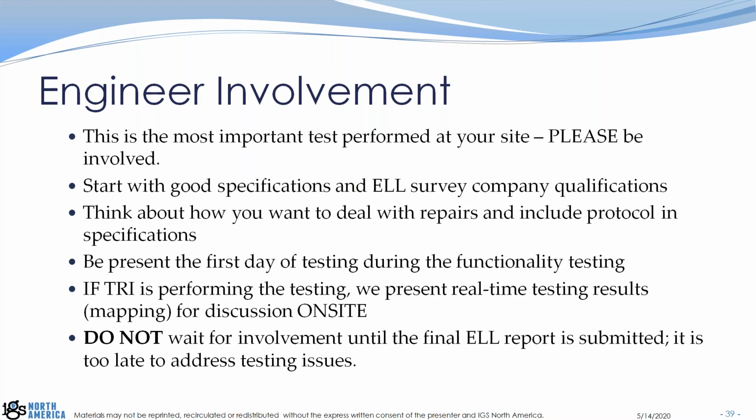Also think about how you want to deal with repairs. For example, I've had some engineers that were really involved wanting post-repair mapping. When we do this procedure, this test, we isolate the hole, we make sure there's no hole around it, but we don't survey after they repair it, for example. We just provide the maps that you saw there. If you want to have a post-repair map, you need to say that as part of your specifications.